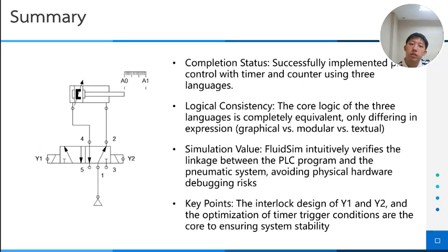The above is the full information process of this homework. Next, I will summarize the completion of this homework. First, completion steps. I successfully used 3 PLC programming languages, LD, FBD, ST, to realize piston control with a timer and a counter, and finished the FluidSim simulation verification.